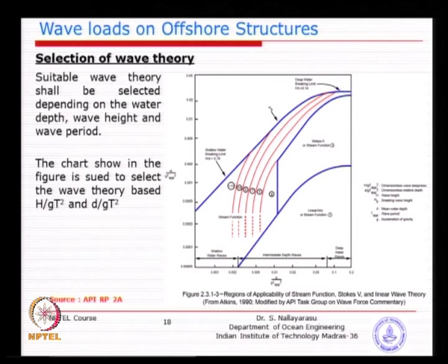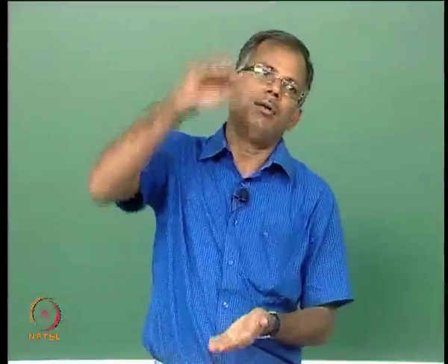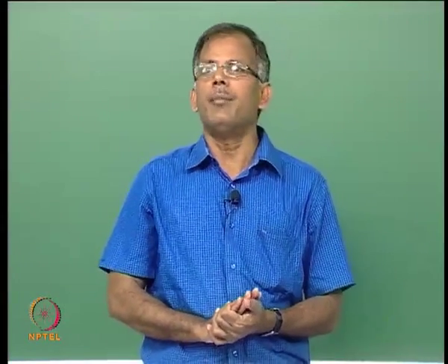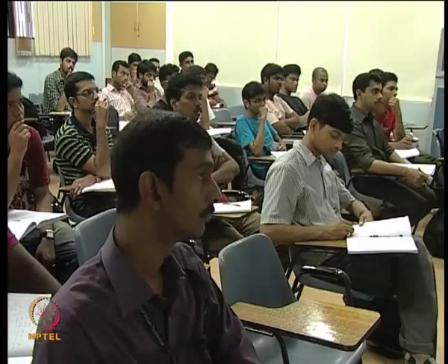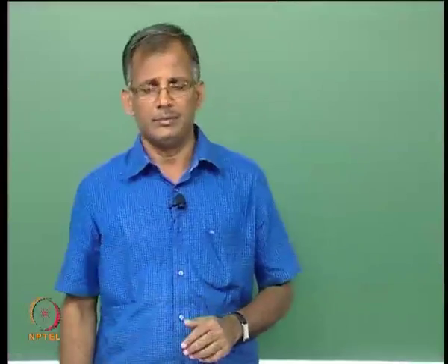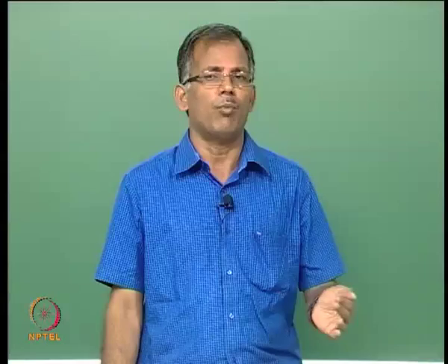So, you can easily see that as the height increases without changing the wavelength, what will happen? The height of the wave is higher and higher, it is unable to sustain and it is going to break. We call it deep water breaking, and basically the waves cannot sustain because the water particle kinematics is so large compared to the speed of the wave. You will see that the water particles jump in ahead of the wave propagation. I think that you will learn more in the hydrodynamics course.